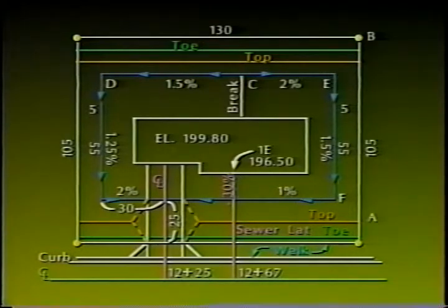1. Determine the ground elevations of the back of sidewalk at the following locations: driveway centerline, southeasterly property corner, southwesterly property corner. 2. Provide the grade percentage between point C and the building pad. 3. What is the slope ratio from point A to the toe of slope? 4. Calculate the cut from the back of the sidewalk to the sewer lateral invert at the property line. And 5. Calculate the distance from the north property line to the toe of slope at point B.